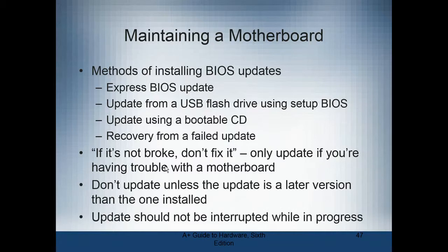It should be a later version, and you have to be very specific. You have to be sure you got the right chipset. Be sure that the update's really an update and it's not a backdate. You need to go forward and not backward with these things. It should not be interrupted while in progress. If it is, you may have made yourself a doorstop.